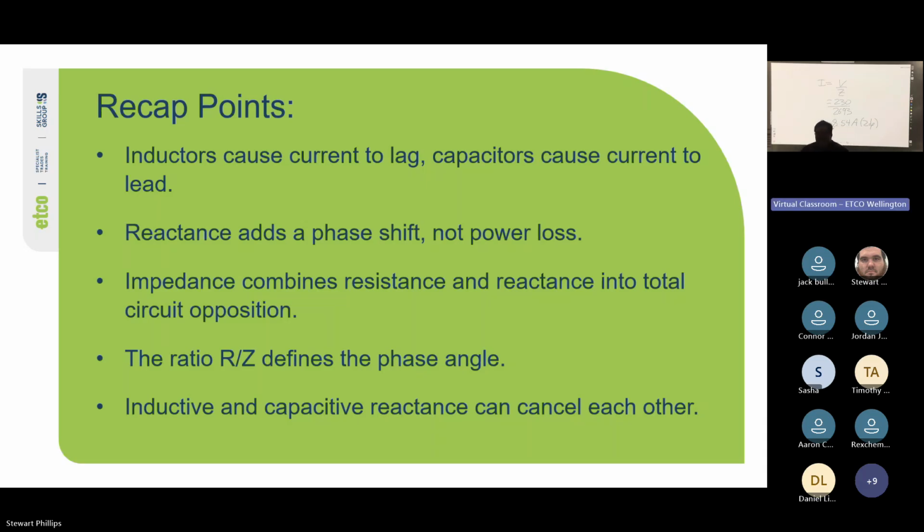So it used to be that we had these huge capacitor banks with all these inductive motors, but now a lot of the motors are switching over to other forms, or we have other loads. Some big apartment buildings, when they first started being turned on, had so many LED lights in them that the power factor went the opposite way. So we had a phase angle shift the other way, and people were concerned we'd have to start putting resistor banks into apartment buildings.